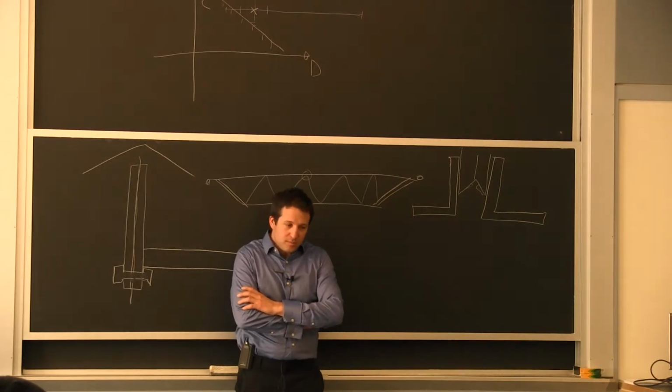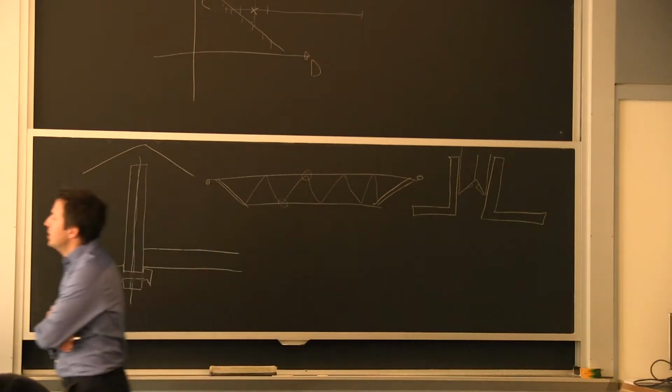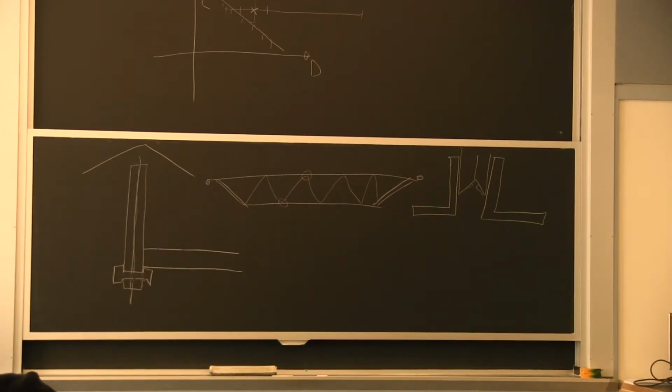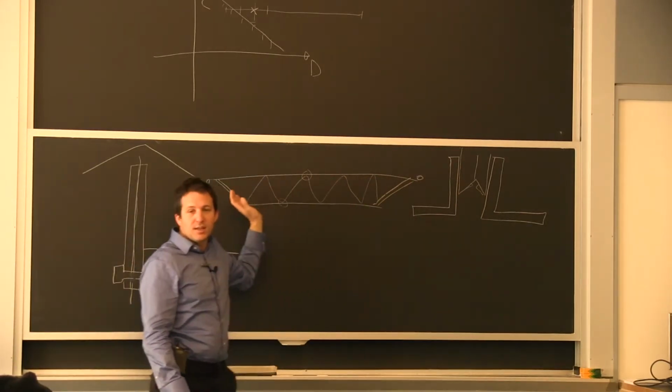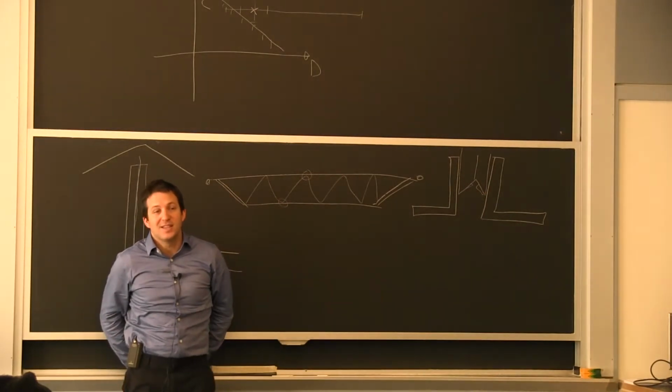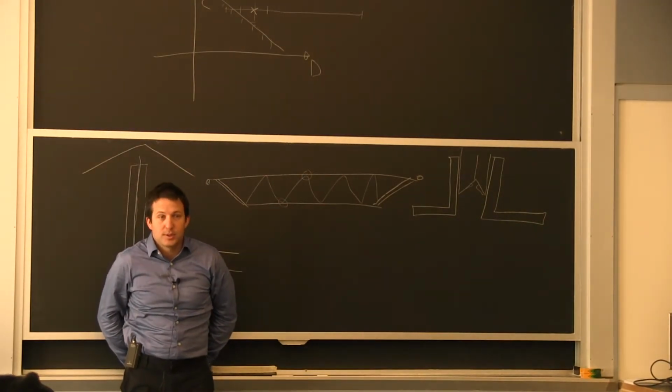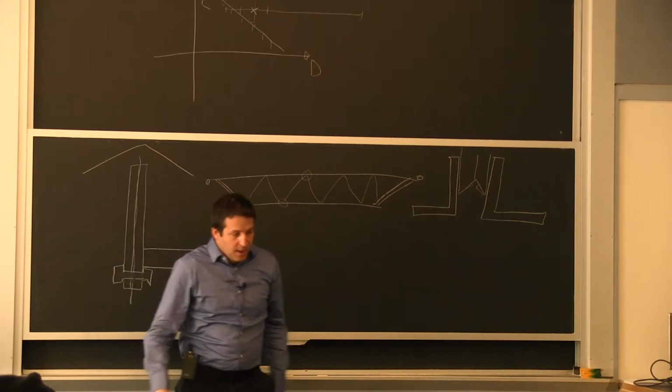Fortunately, in terms of inspection, it's not too hard with a trained eye to determine here if you have fusion or not. The only problem is there's so much fabrication that how much are you going to have an independent inspector come and look at these? Now, again, when they do this, most of the time it's only for the center portion of the joist. When you get to the end diagonals, it's a different detail that is more reliable. So that's really the difference.